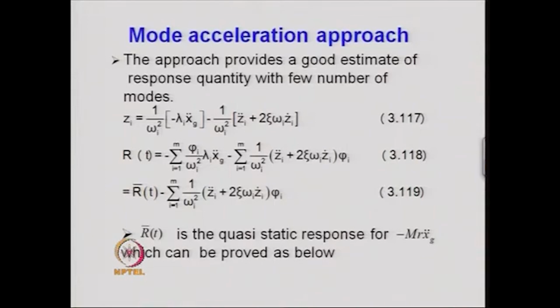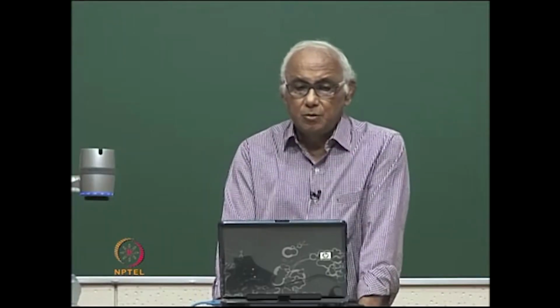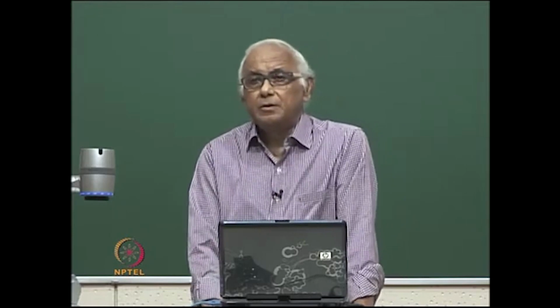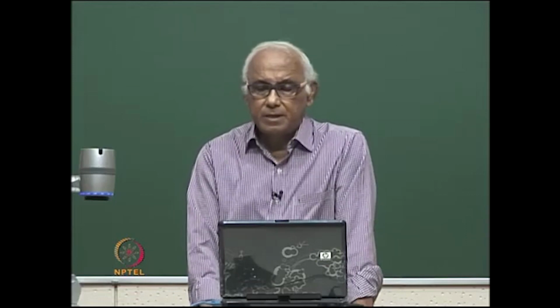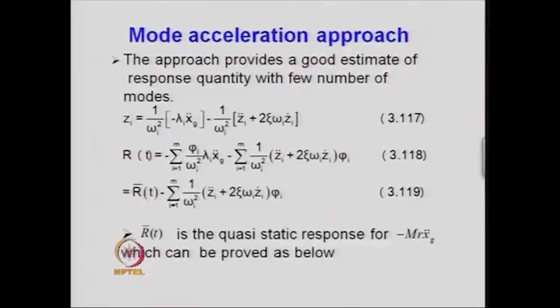Now, let us come to another method called the mode acceleration approach. It was evolved because we wish to obtain a very good response of any type, that is whether bending moment, shear force or displacement, with a smaller number of modes. That is our intention.